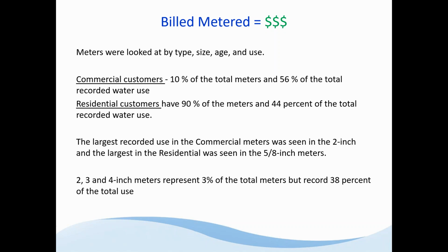Just because it's a 6-inch meter doesn't mean it's going to be the biggest user. In the case of this system, the 2, 3, and 4-inch meters represented 33% of the total meters in the system, but recorded 38% of the total use. Those meters obviously are critical in their system and to their revenues.